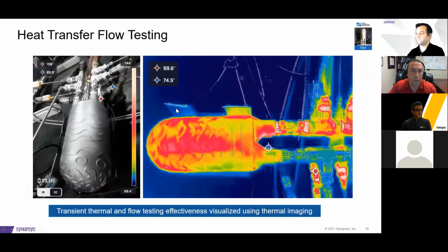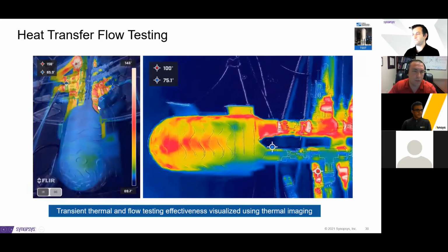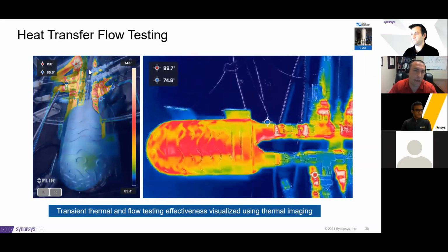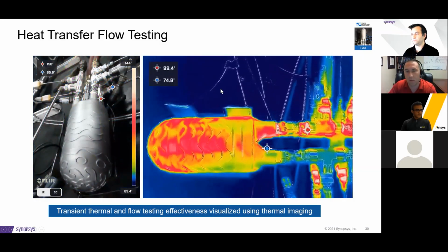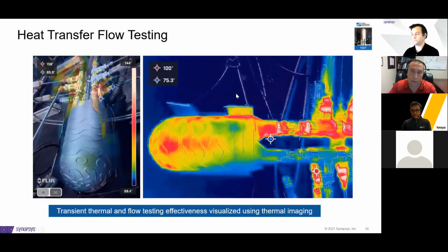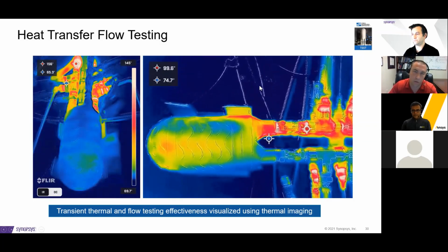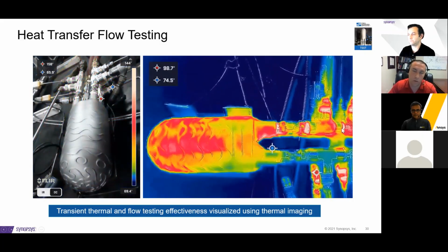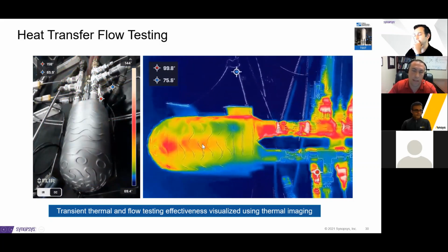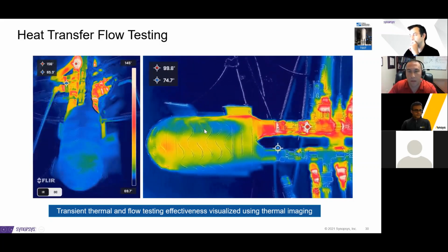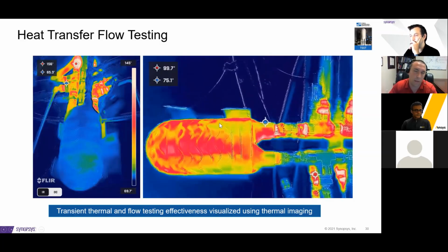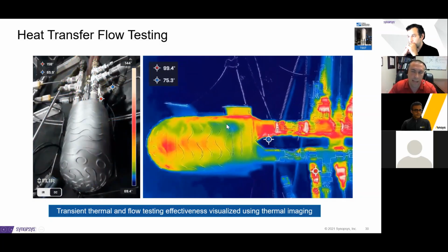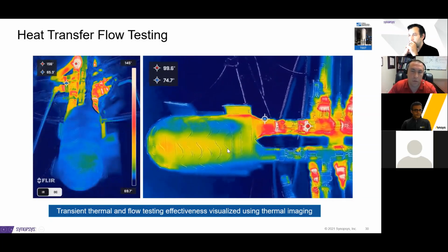We also took some thermal imaging data. Here on the left, you can see the heat exchanger, and then overlaid the thermal image, you can see the hot oil coming into the heat exchanger as well as the cold fluid. Here on the right is where we were flowing just the hot oil and not flowing any coolant, and letting the external casing soak in that heat and become very hot on the outside, shown here. Then when we turned on the cold fluid flow, you can see how much that heat dissipates and the external housing rapidly cools down. And this information can be useful for getting a feel for how temperature is distributed throughout the heat exchanger, and can be used to look back and feed into a heat transfer analysis.